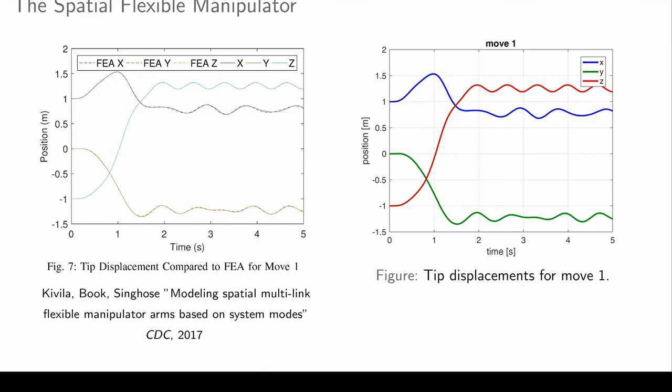Okay, thank you very much. I have just one more small question. You said it's quite difficult to use inverse dynamics, so I'm wondering how long these simulations take to produce, essentially the forward dynamics. For these kinds of simulations, we can accommodate more or less 2 seconds of computer simulation for 1 second of real simulation, with a step size of 0.01. This is more or less to give you an order of magnitude. Okay, thank you.